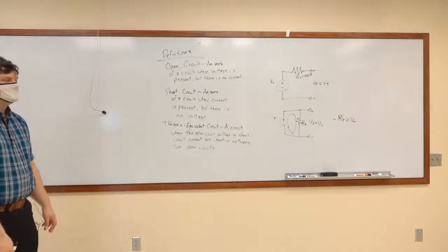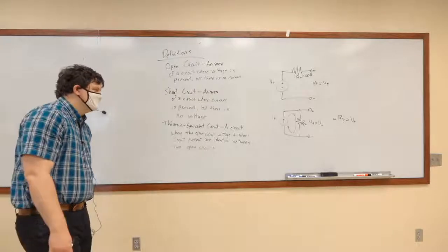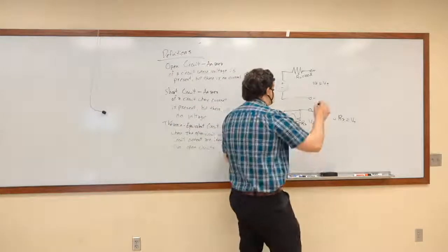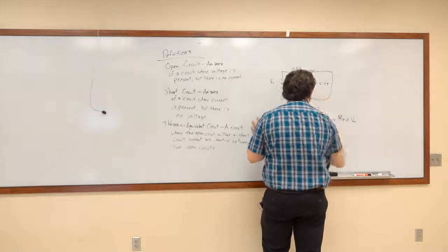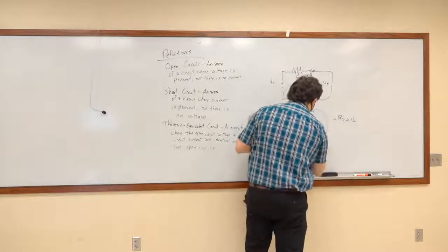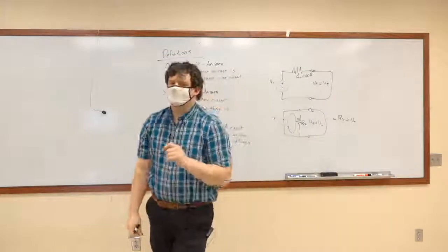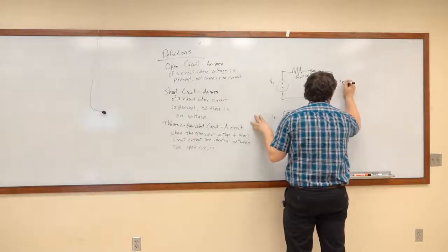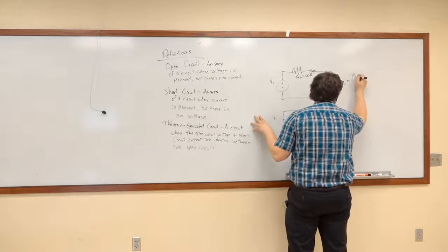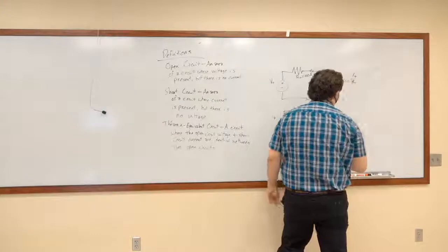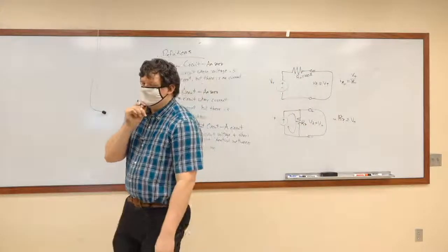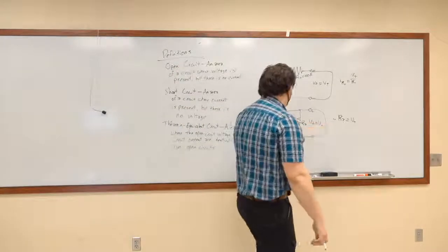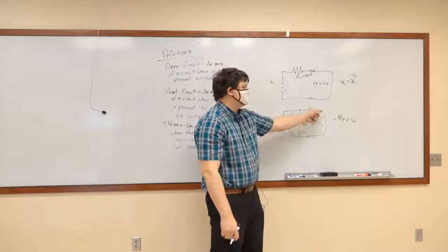So we need that to be true. But we also need it to be true where if we plug in a short circuit wire between both of these terminals, that it has the same current. Now we know for this system that current, IRT, is equal to VT over RT. We just derived that a little bit ago. With that equal to VT over RT, well, if we short this, how much current is going through that shorted wire?